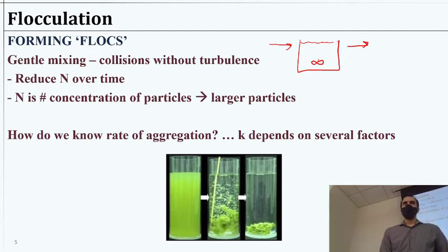We do not want turbulence. We just want pretty much laminar flow, or probably laminar flow with gradients of different speeds. So there's that gentle mixing, but there's no shear forces to strip the particles back apart. The goal is to reduce the number concentration over time.